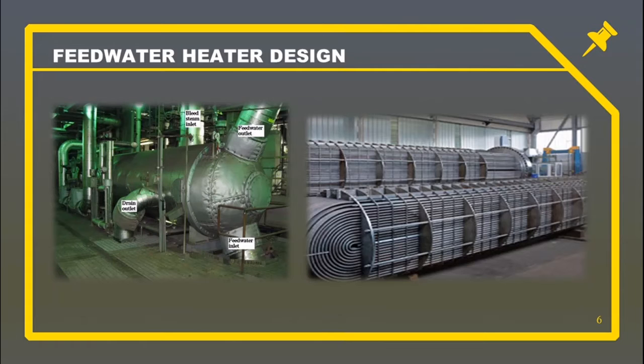These alloys have excellent thermal conductivity, but on the other hand, they have the problem of copper carryover and ammonia attack, which may require a complex boiler cleaning after short intervals. To avoid all these problems, stainless steel tubes are invariably used for low pressure heaters. Stainless steel is unaffected by all operating conditions, except that it is susceptible to chloride-induced stress corrosion. For high-pressure heaters, the most common materials are carbon steel, stainless steel, and Monel metal.